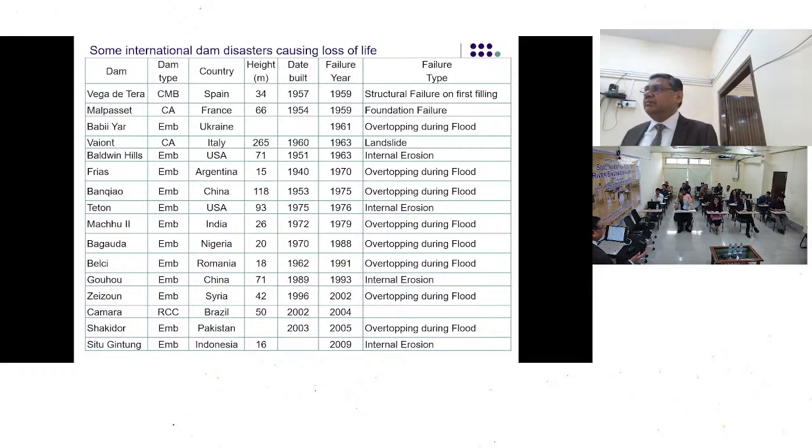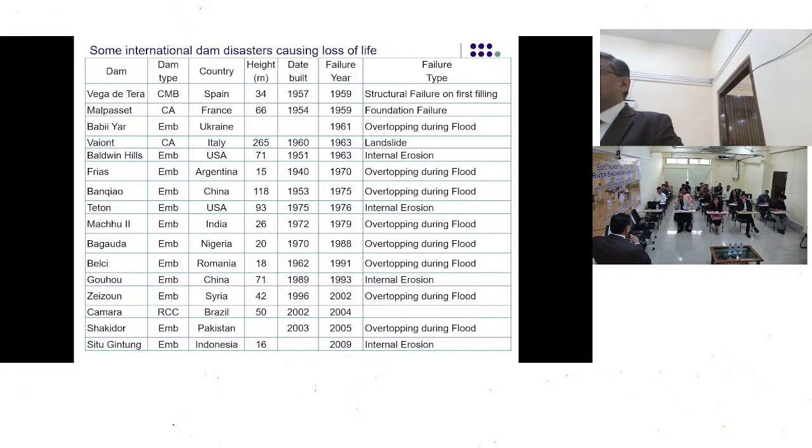Now imagine a dam, let us imagine a kilometer-long earthen dam. It has been built over a period of time, so height-wise as well as length-wise there can be material variability. Then there can be variability in the construction practice. There can be variability in the borrow area material, and there can also be variability in the moisture content which has been put into the material when it was being laid.